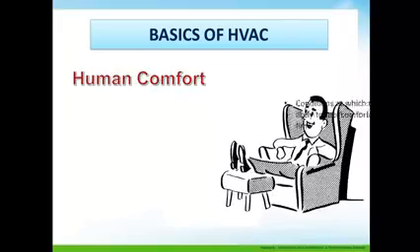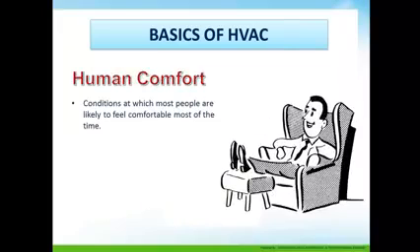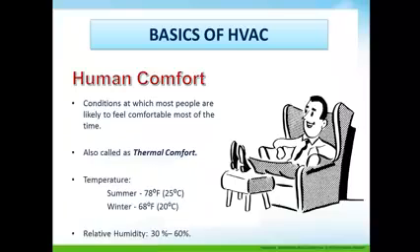Human comfort. The condition at which most people are likely to feel comfortable most of the time is also called thermal comfort. The temperatures are 78 degrees Fahrenheit in summer and 68 degrees Fahrenheit in winter, with relative humidity of 30 to 60%.